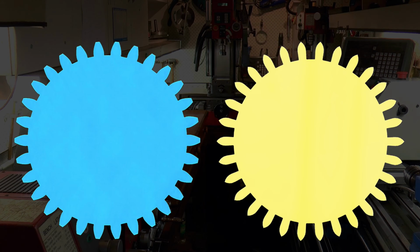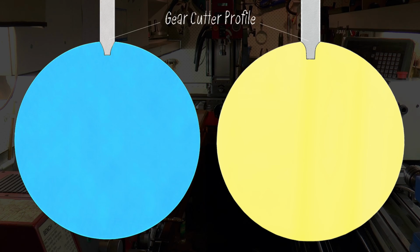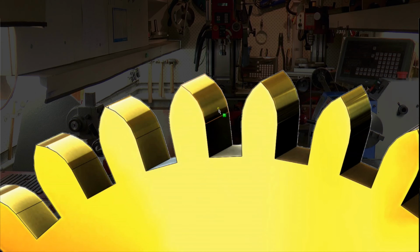But if we take a step back and look at the big picture, we can make a few broad statements. Firstly, that gear teeth are formed by removing the metal between each tooth. So what we'd like to make is in fact the profile defined by the gap between each of the teeth. Secondly, if we take a close look at that gap and exclude fillets from the discussion for the moment, we can break it down into some fairly straightforward elements of curves and straight lines. If we can mathematically define each of those elements in a simple way, then we've got everything that we need to generate the profile of our cutters.